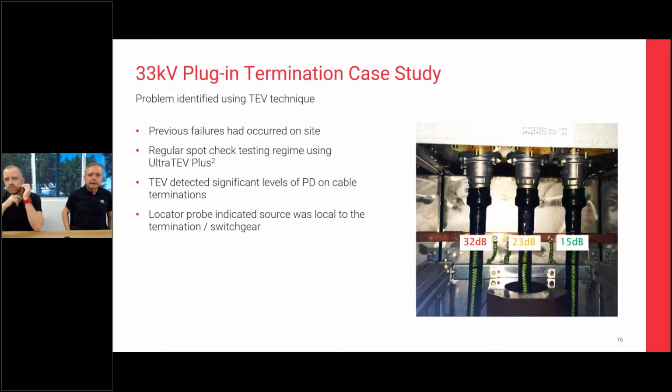It gets a little bit trickier when we start seeing partial discharge inside the cable around the termination area. Often, as in this case study, we start seeing a failure, and then we start seeing maybe a population of defects happening, or a site defect. If we think back to our statistics, a lot of problems are associated with workmanship, but there are also problems associated with design defects.